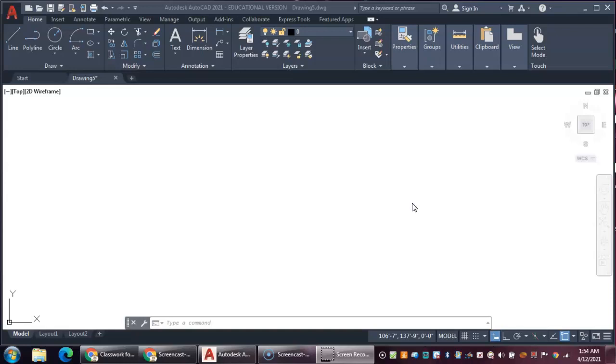Just follow along. If you don't have it open, like I do, go ahead and open up drawing ball field chapter 6. You want to make sure the limits are set to 512 feet by 384 feet, and your snap is set to 10 feet, and your grid is set to 20 feet. Just as a refresher to remind you how to do that, I'll type in limits.